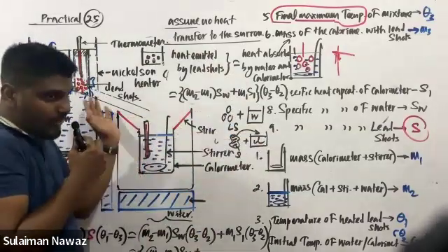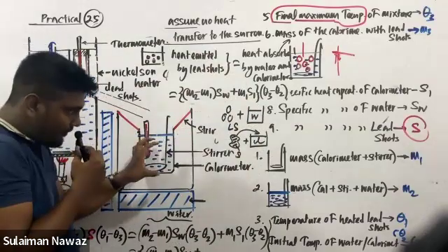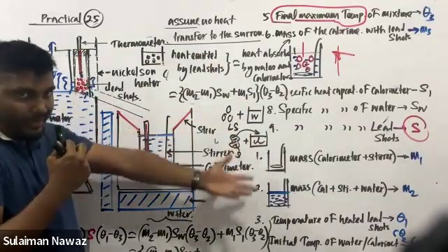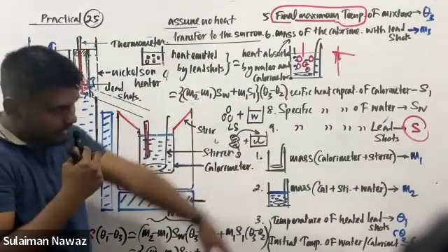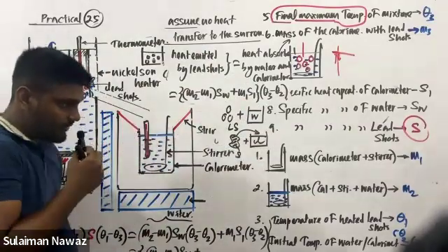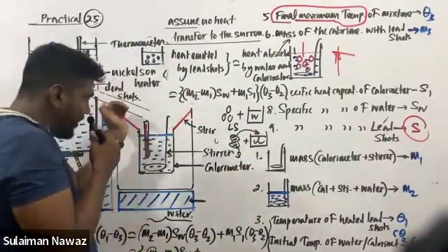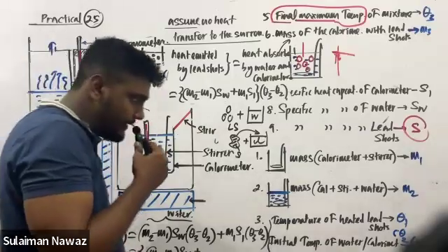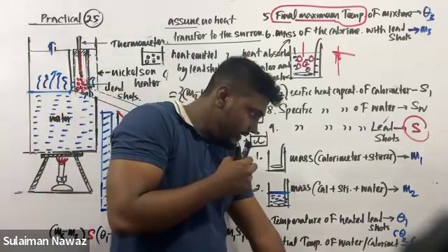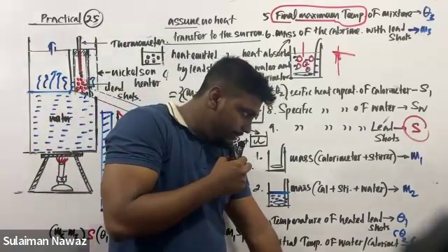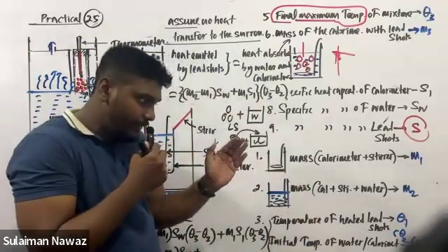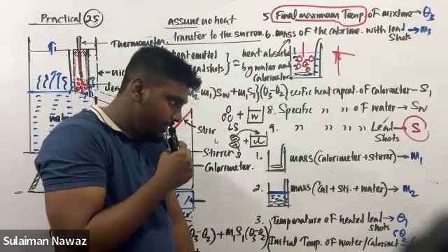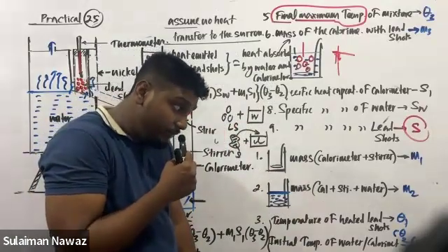You understand, right? The mass you use for the calculation and the actual mass of the water is different. So you want to very carefully, slowly allow the lead shots to fall into the water, because the mass measurement has already been taken, and otherwise it can be inaccurate.